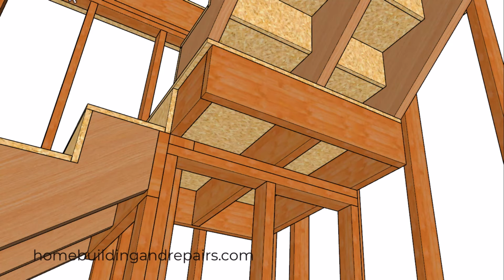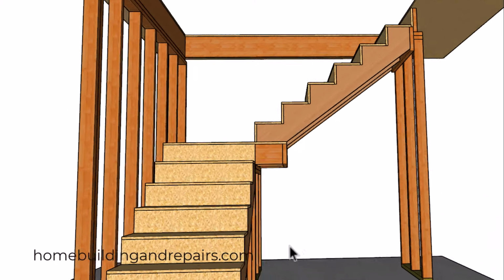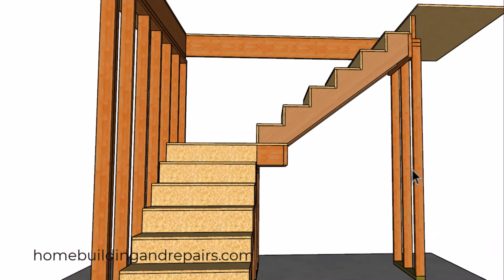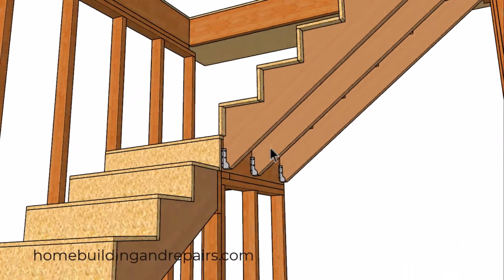And this design here will provide us with an open section underneath the stairway, but it's not always going to create a nice looking line here. We're kind of coming out here and going up and then in this direction. But we can fix that, right? By using some hangers and cutting the stringers a little differently. And in this example here, the joist can run in either direction.